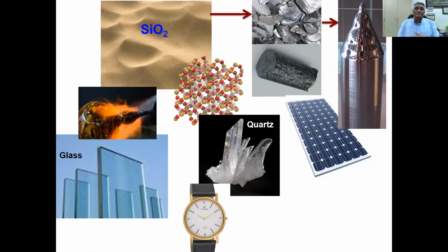So the difference in both cases will be that the silicon panel made out of polycrystalline silicon is inexpensive. The single crystalline silicon wafers or photovoltaic panels are very expensive, but what you get with polysilicon is about 13 to 15% efficiency of conversion of the solar radiation. Whereas if you get a silicon panel using single crystalline silicon, the efficiencies can be pushed up to 26%. So it depends again on applications. What kind of applications are you looking at?